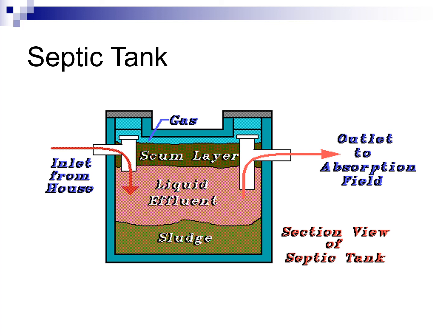The purpose of the tank is to give solids time to drop out of the liquid, because the fields are not designed to take solids. They're really designed to take liquids. So that's also one of the reasons why septic tanks have to be maintained and periodically pumped out, because if that level of sludge rises to the point where it gets into the outlet, then that will also damage the fields, and that will be a very expensive repair.